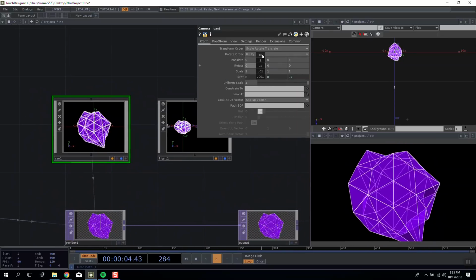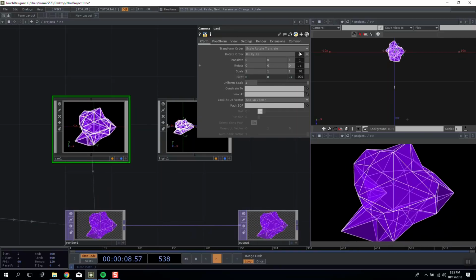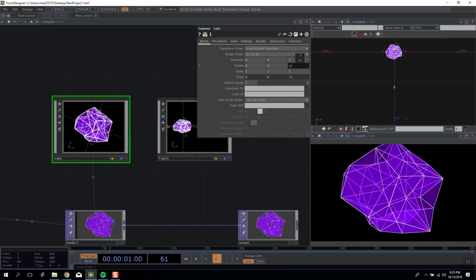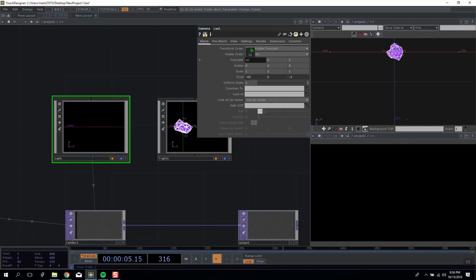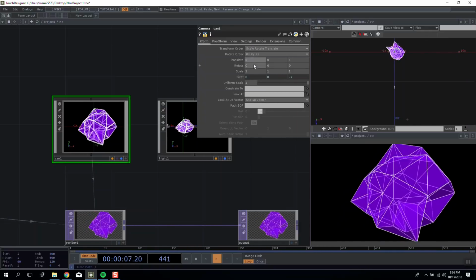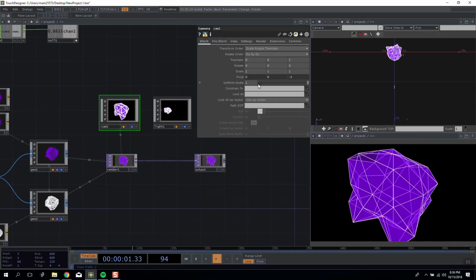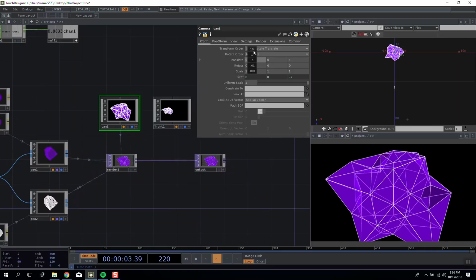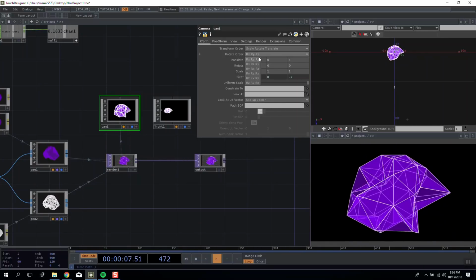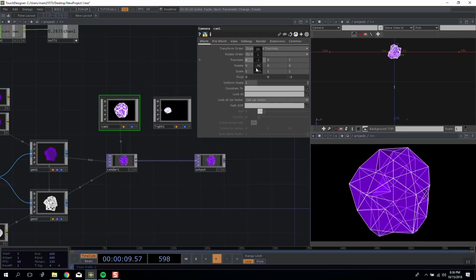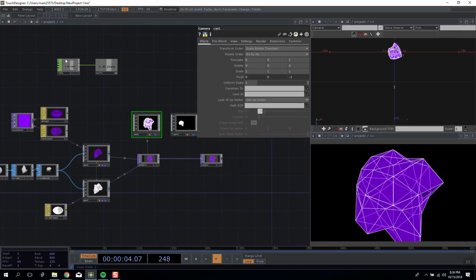And as I showed, if I rotate my camera around any of the axis, it is going to correctly update its position. So for example, the top, or up and down. Wrong one, up and down. And again, just to refresh you, when I hover over a value, I'm just pushing my middle mouse button to bring up the quick parameter menu, and then I keep holding the mouse button, move my mouse up or down, and then left and right, all the while holding middle mouse.